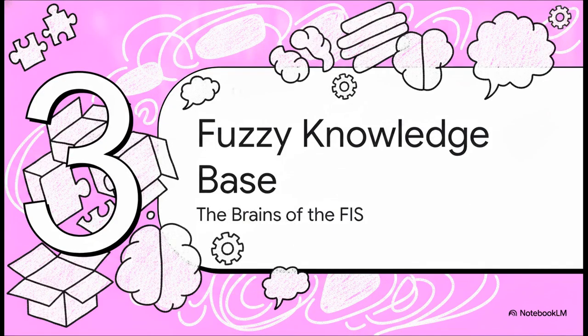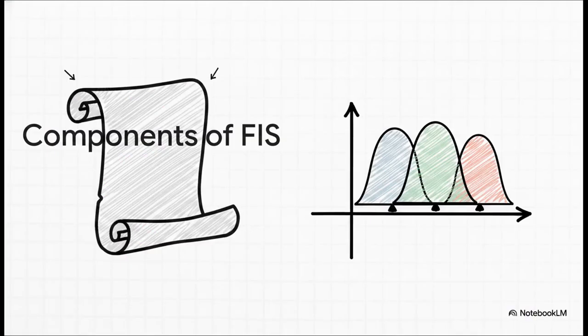Section 3. The fuzzy knowledge base. Let's crack open that middle box, the real brains of the operation. There are 2 conceptual components that store the system's logic. First up is the rule base. This contains the fuzzy if-then rules that usually come from human experts or numerical data. Think, if the temperature is hot, then make the fan speed fast.